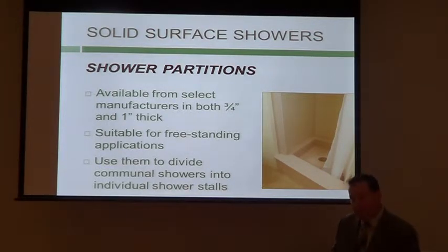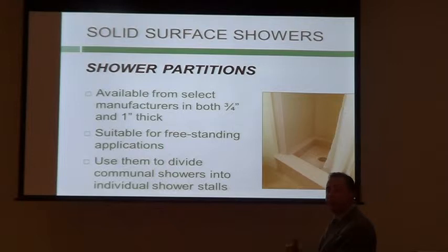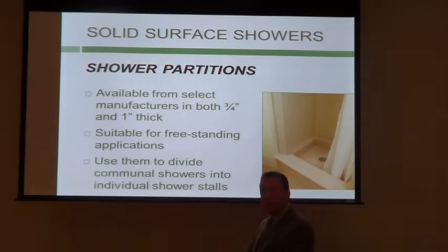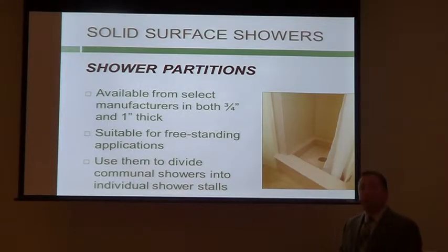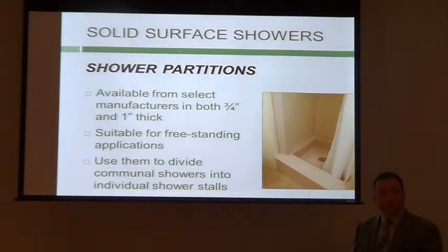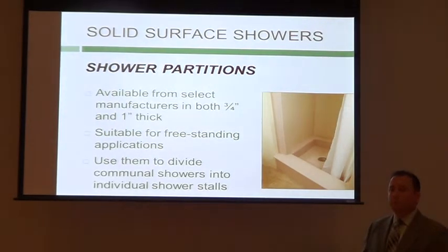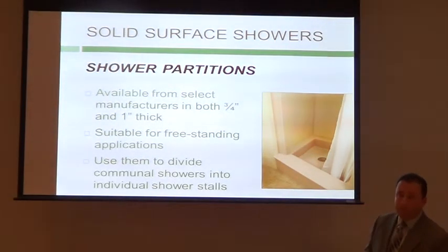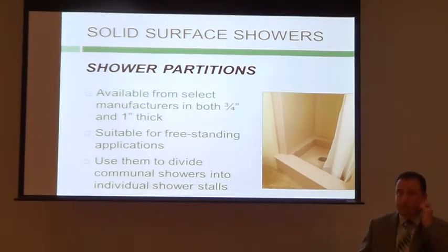in solid surface. So if you think about, I'm doing my solid surface vanity top, I'm doing my solid surface shower, now I can also take the same color scheme out into that drying off area or that enclosure where they're entering into the shower. Now, those areas that are out there in the room a little bit more are going to be more susceptible to impact, people leaning on them, bumping into them and whatnot. So we do recommend at least a 3/4 inch thickness. 1 inch certainly is stronger, costs a little more, but you would not want to settle for a 1/2 inch thick wall panel or door. That gets a little weak. I've seen those fail, especially in a college setting or even in a hospital setting where people are falling into them. You want the strength of the added thickness.